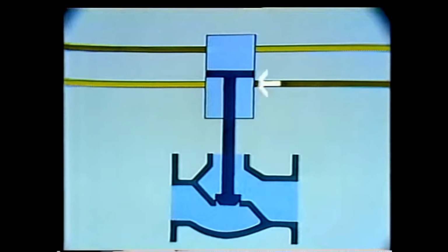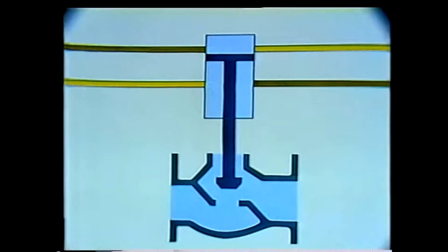If pressure is applied under the piston, the disc moves up, opening the valve. The top side of the piston is vented, allowing the piston and valve to make a complete stroke. The reverse takes place to shut the valve.